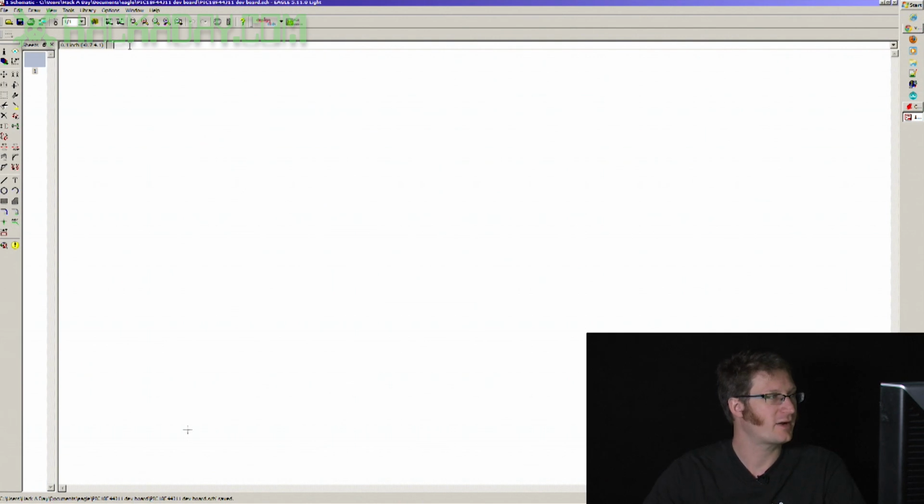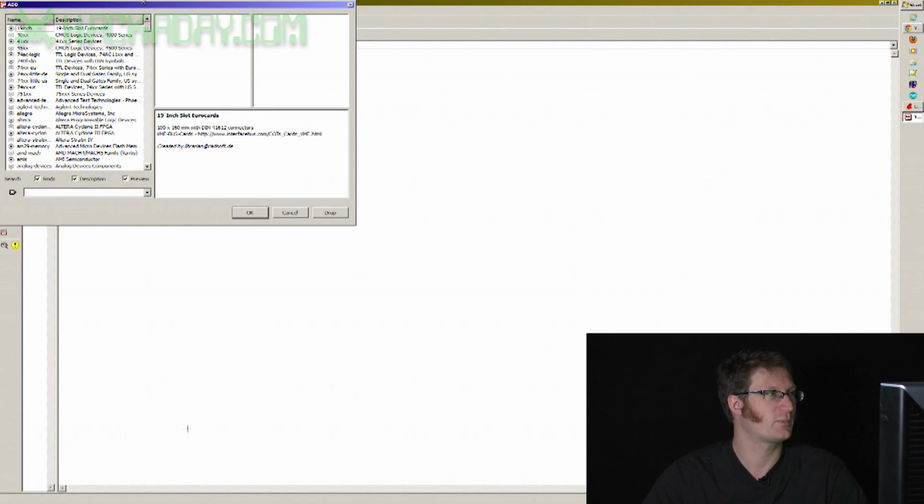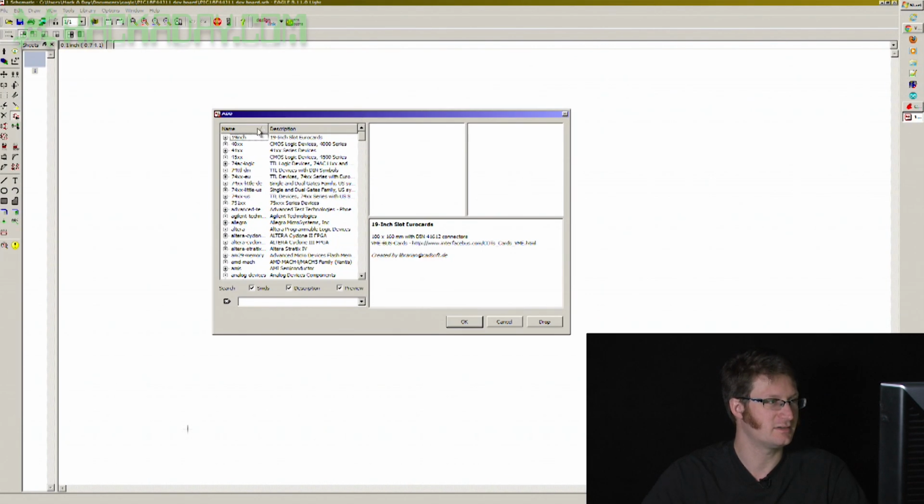Okay, in the text box here, I'm going to add a part, and I just type add. One interesting thing that I'll say about Eagle CAD is you don't actually usually have to type in the whole thing. So AD, enter. Yes, that brought up the entire box here. So I want to add an LED.